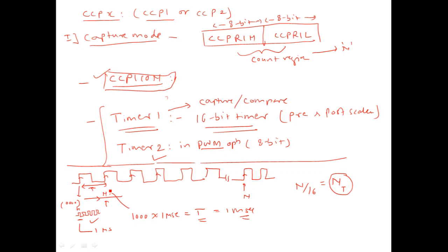But when you go to the ISR, let's see, when it is interrupted here, for example, in the ISR you can reload the count to 0. You can reset the count in the timer to 0 and restart the timer. So that the next time again that count will be captured, and the difference will be dependent upon this time interval.